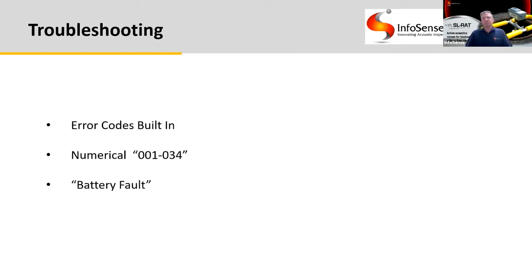Error codes will present themselves if a condition exists in the device that recognizes as a fault. Some error codes will come up during the startup sequence and read as a 6-digit number. If you see an error code, try turning the unit off, wait a few seconds, and turn it back on. The code may clear, and you are good to continue working. If the code persists, the unit will need to come in for service. These error codes do designate more serious failures, and again, if they don't go away, you'll have to send it in for diagnostics.